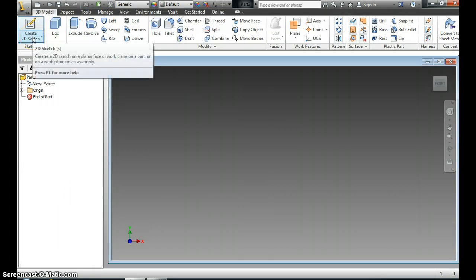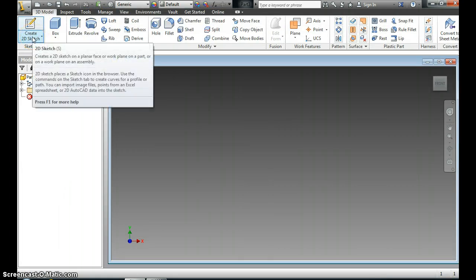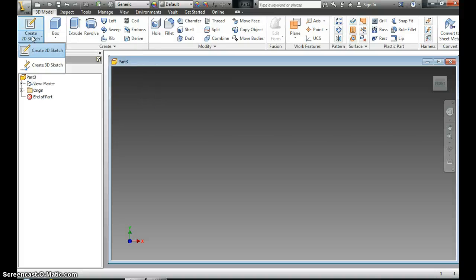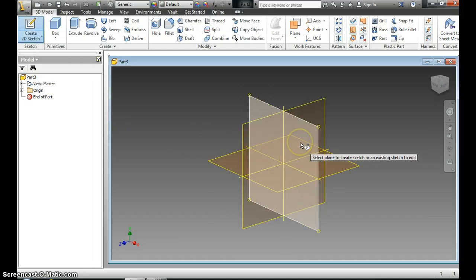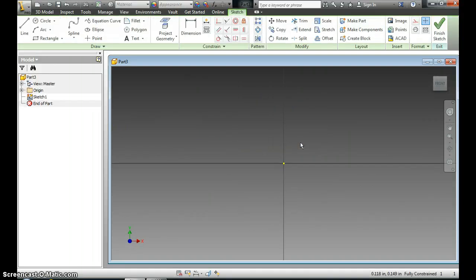Now the first thing I want to do is create a sketch plane that I can create the front of my shape on. So I'm going to click 2D sketch, and I'm going to choose my front face. And I'm looking at my pegboard toy. The front face is the face that's to the left. And if I look at my measurements, it says create a pegboard part 3/4 inches in height, 5 3/4 inches in width, and 3 inches in depth.